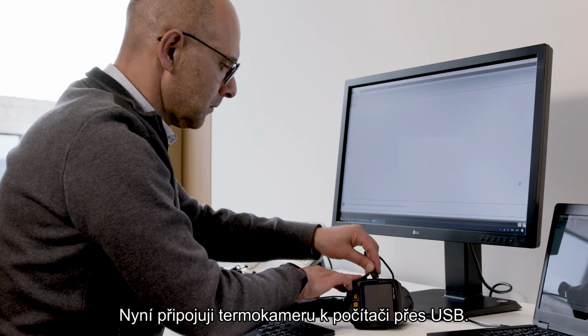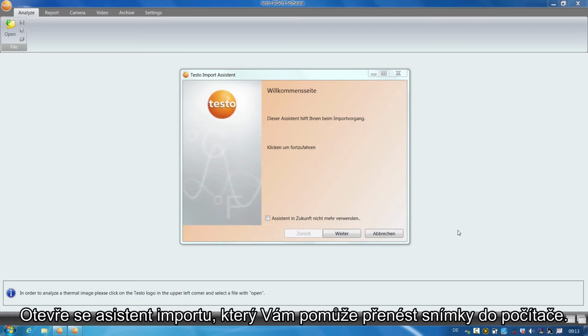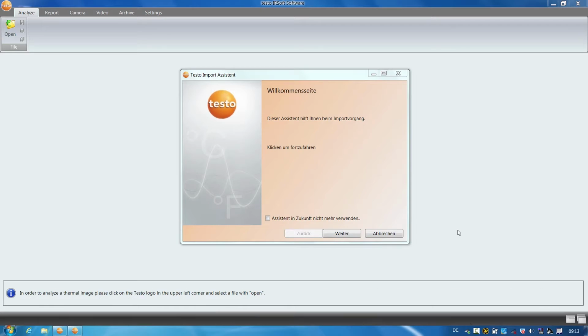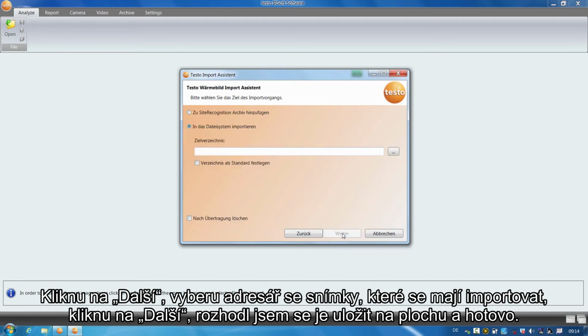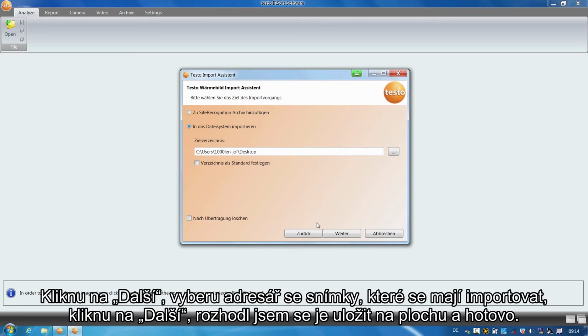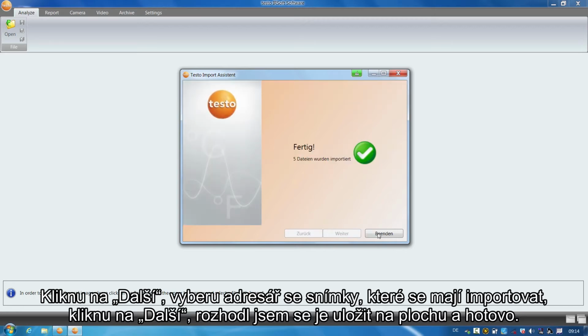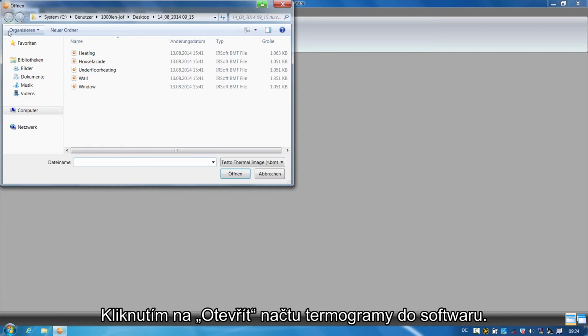I now connect the thermal imager to my computer by USB. The Import Assistant opens in order to assist you to transfer the images to your PC. I click on Next, select the directory with the images to be imported, click on Next, decide to save them on the desktop, and Finished. I click on Open in order to load the thermal images into the software.